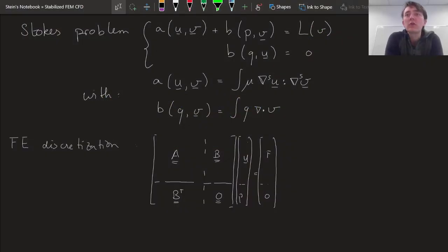So now that we've discussed where mixed formulations often come from, namely constraint minimization problems, and now that we've talked about the necessary and sufficient conditions for existence and uniqueness of a solution, namely the LBB conditions, it is time that we start talking about how to obtain actual approximations to these solutions by means of a finite element discretization.